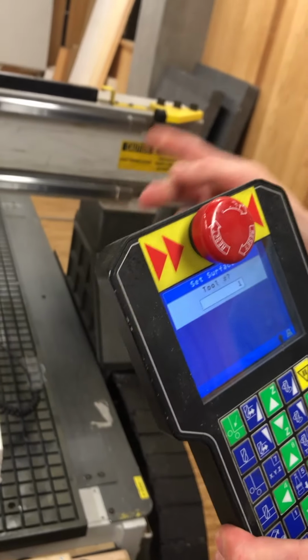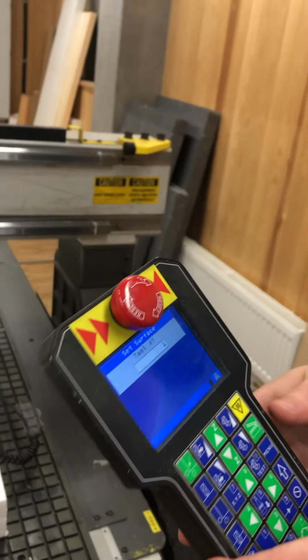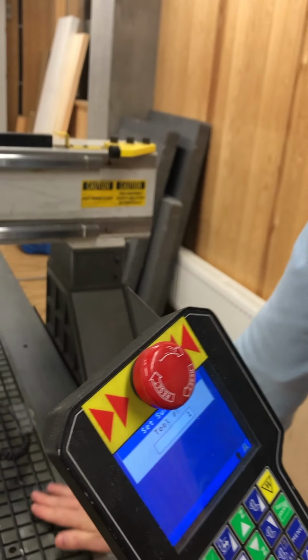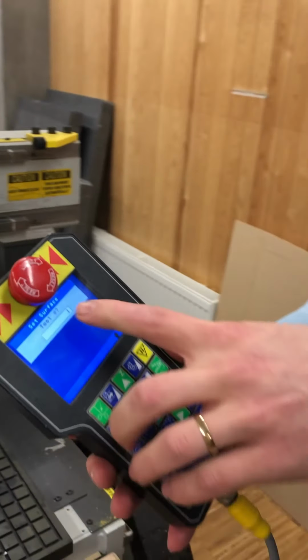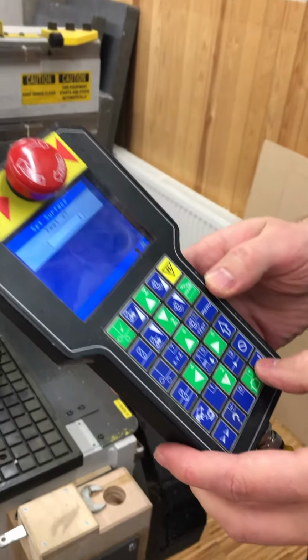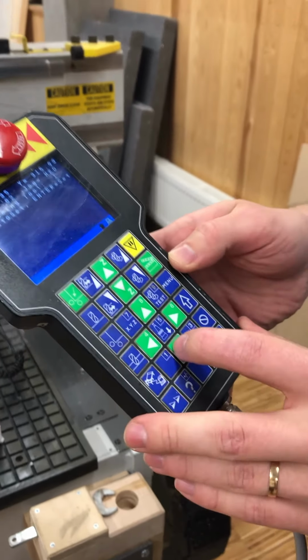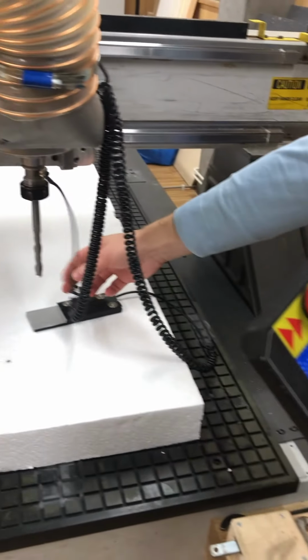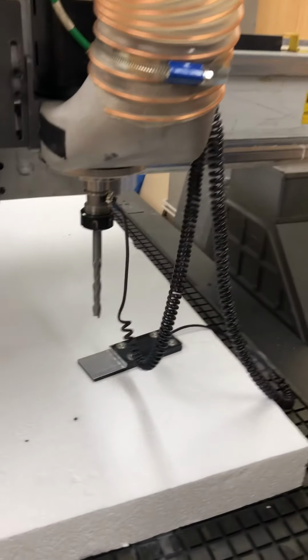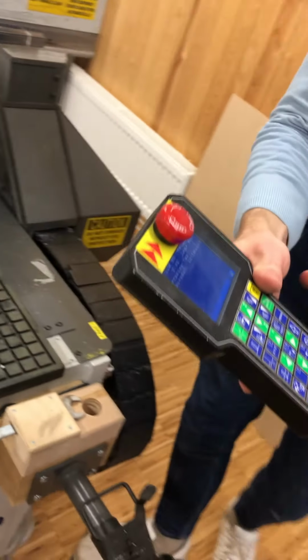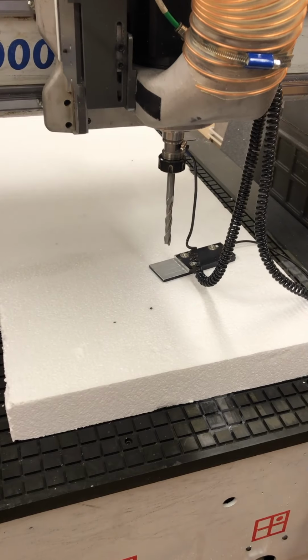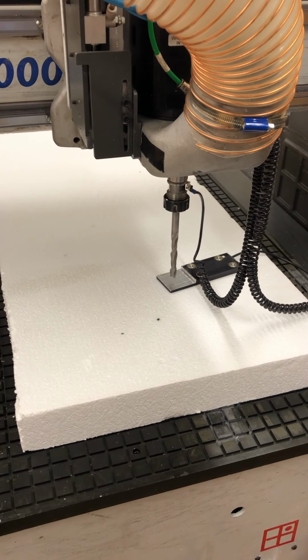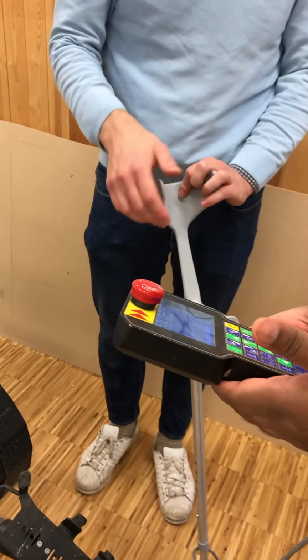And each different tool has a different surface depth. They all share the max cutting depth, but one will need to set the surface depth. So tool number is 1, that is correct. We can press enter, and then we can do like we did before. So jog it a little down. Oh, sorry. Can I do it? Yeah, of course. Oh, stop there. And then you can press and hold the 0.